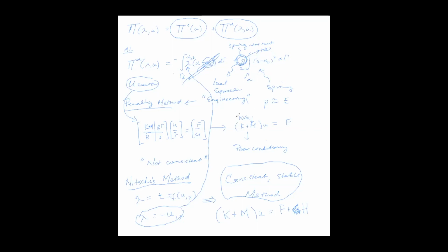So is there any reason not to use Nitsche's method all the time? I'm only hearing pros. Are there any cons? The con for Nitsche's method is that it's complex, because modeling the traction for complicated problems can be difficult, like for shells and beams. I wouldn't say it's impossible or anything. It's just not as simple as penalty.